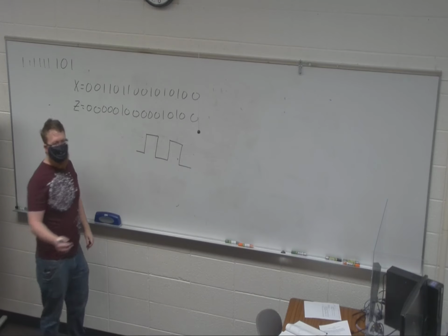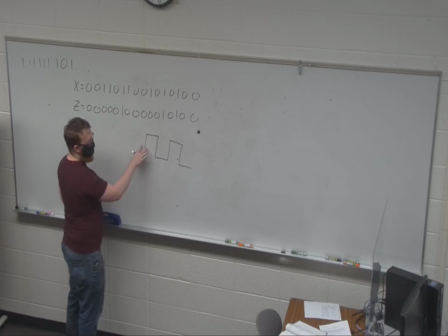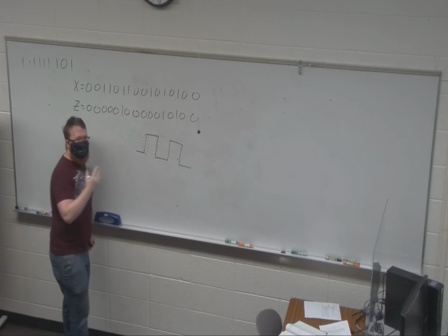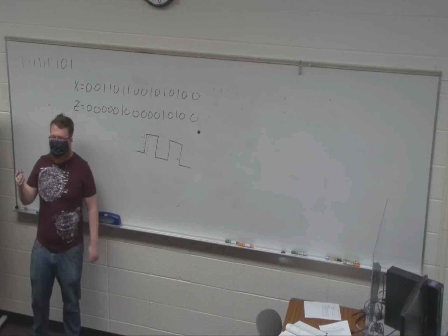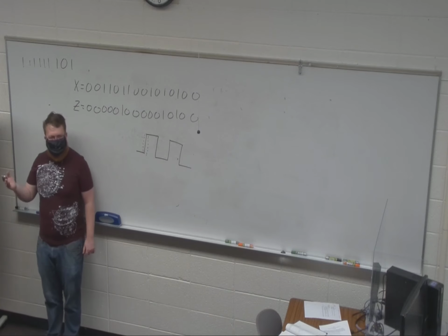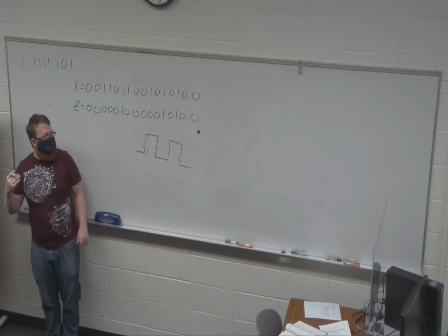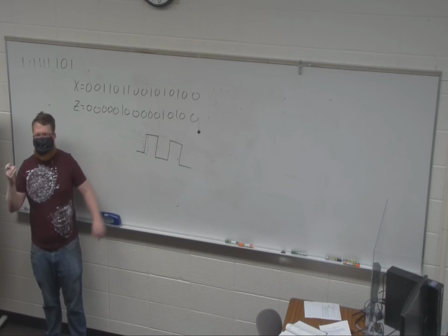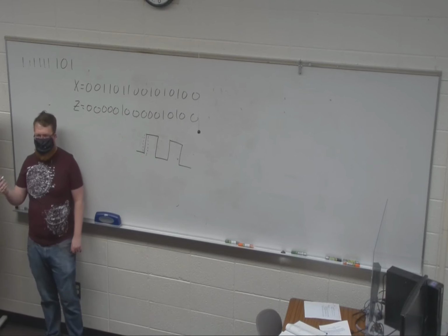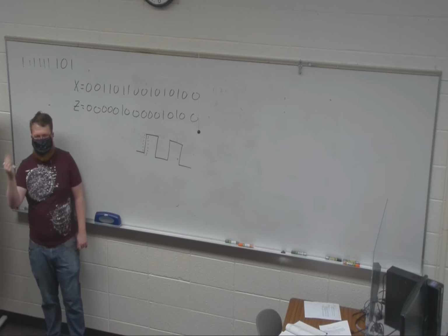The first one we call jitter, which is where this rising edge of the clock and the falling wants to happen here, but it could actually happen anywhere in some window. So your clocks that are generated from something we call PLLs, that phase locked loop, are going to have some specification for what their jitter is, and that's going to be that clock bouncing back and forth.